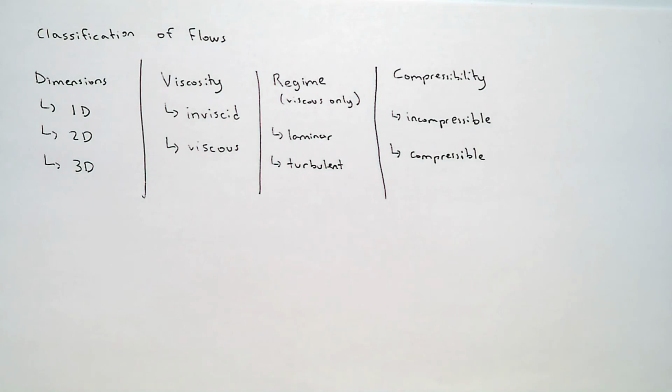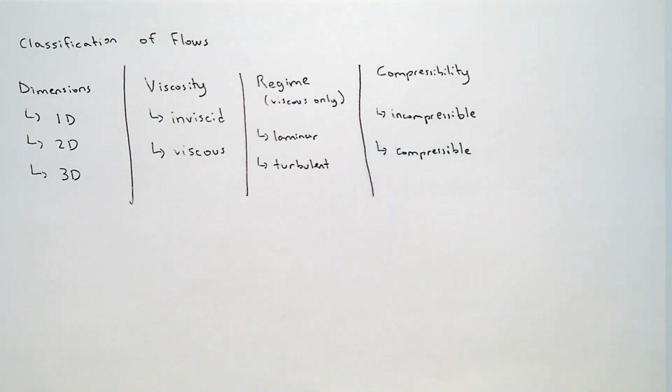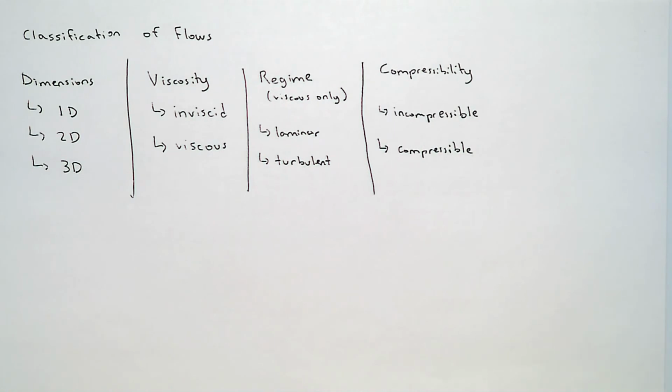In other words, if I were to disperse a gas here, it's not going to stay here, it's not going to stay clumped, it's going to fill up the container. But now, does the mass of my gas increase as it fills up my container? No. Only the volume increases. So if my mass doesn't change but my volume changes, that means that my density changes. So if the density of a gas changes constantly, we cannot treat it as incompressible. So you'll see for this class that our liquids will be treated as incompressible, our gases will be treated as compressible, and that's assuming that we actually get to a point where we can talk about compressible gases.